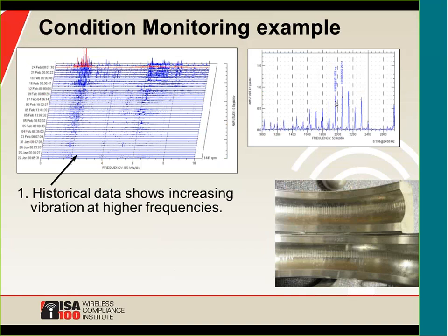One example of condition monitoring in a roller element bearing is presented here. As you can see with the waterfall spectrum in the upper left corner, over a period of roughly a month, about 30 days, the spectrum changed, the characteristics changed, and as we got to the end there, a failure, which was indicated by the red line, came about.